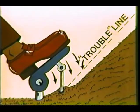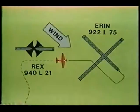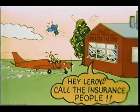Also, to avoid surprises on your landing rollout, be sure to check your brake pedal pressure before you enter the traffic pattern. If your brakes feel mushy or soft or go to the floorboard, you know you've got a problem. The best action to take in such a situation is to arrange to land on a longer runway and, if necessary, at another airport. Also, make sure that you land as nearly into the wind as possible. It's very poor technique to learn about brake problems when you're on rollout.